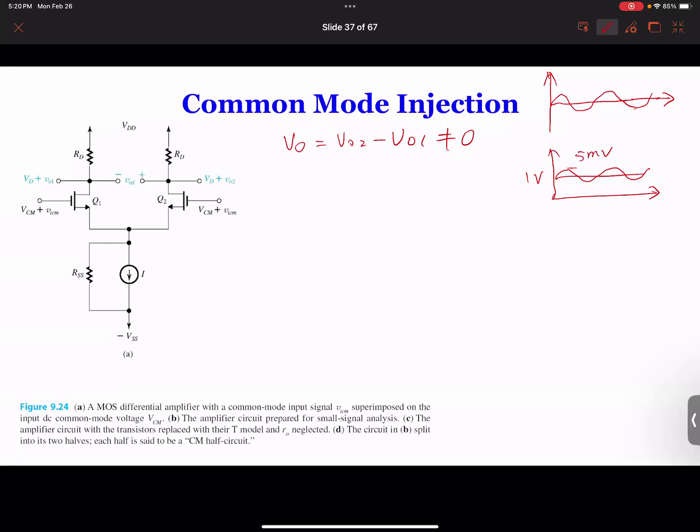So over here, what we can do is first draw an equivalent circuit. Earlier, one student came to see me asking how do we know that the circuit is representing DC or AC? If you look at the circuit, this is representing a DC circuit because you have voltage on both sides. So when we draw the AC signal circuit, we'll have the DC current open, and then we have the DC voltage short. So in this case, we're going to draw the AC circuit.